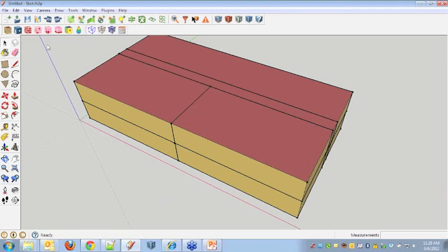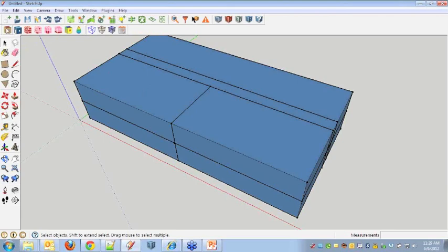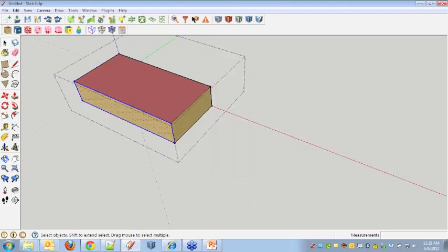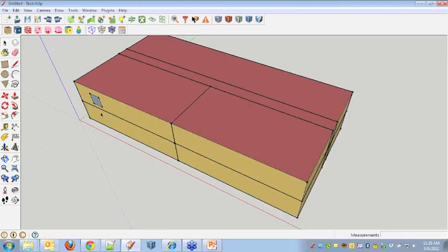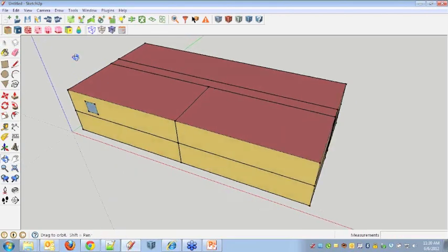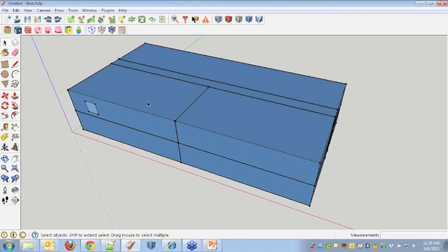And just to show you what this means, we have different render modes. The first render mode I was in is render by class. And walls look like walls, roofs look like roofs, and we even have a special color for windows. So as you draw windows, they'll be transparent because they get classified as a subsurface, and all that happens automatically. This other render mode renders by boundary conditions, and this tells you when you run the simulation what is the surface exposed to the ground temperatures, to the air temperatures, or some other interior surface.